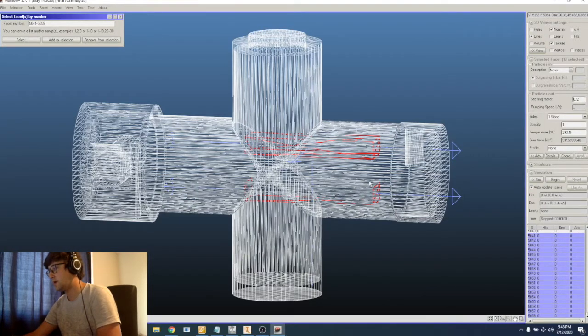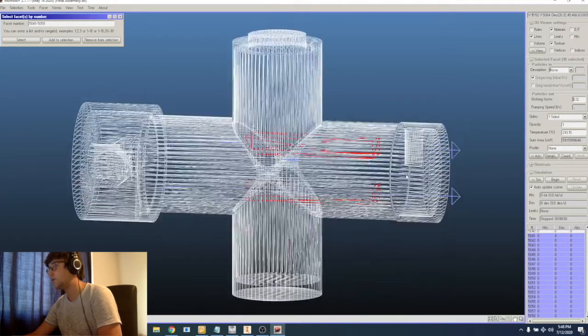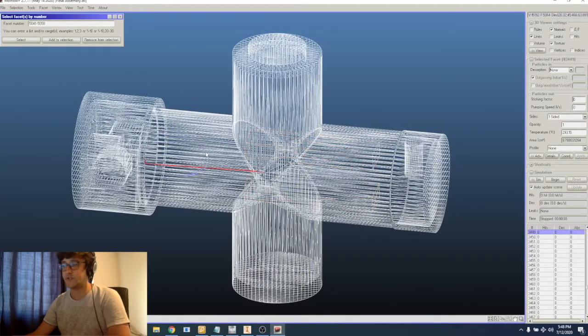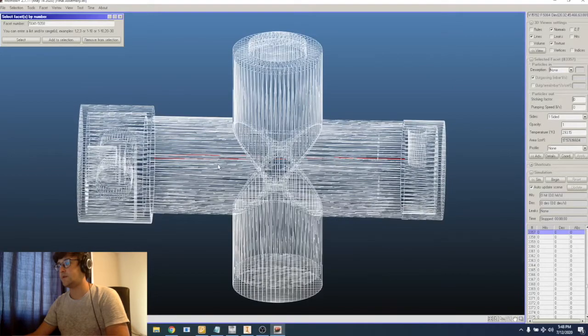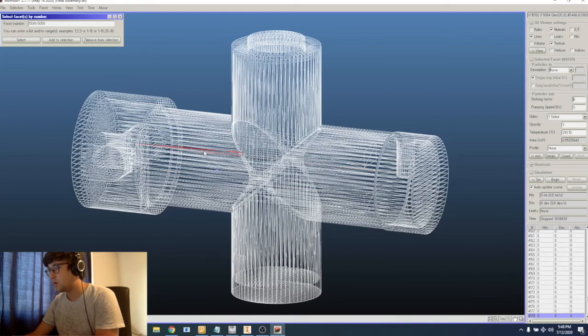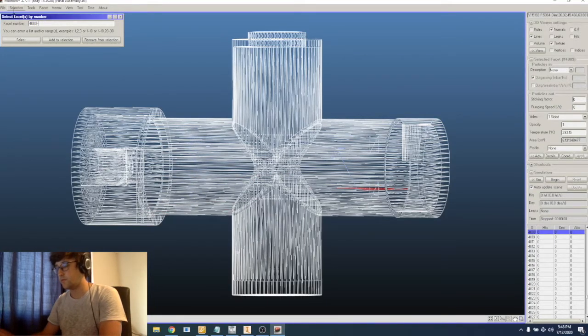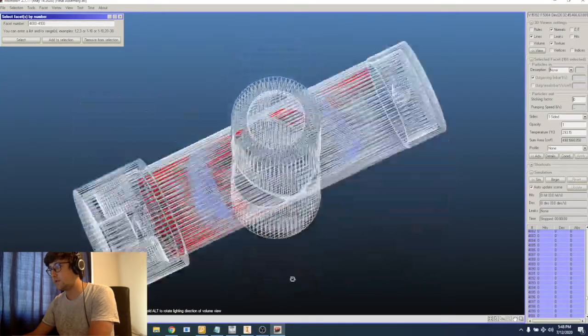Now I have some pumps that I've assigned, some sticking factor, that's good. I still don't have any vertices that are desorbing, so nothing's going to happen if I run the simulation. So I'll assign a bunch of interior surfaces to desorb. Here. Okay, we'll go just arbitrarily 4,000 to 4,100. So that's some interior surfaces.